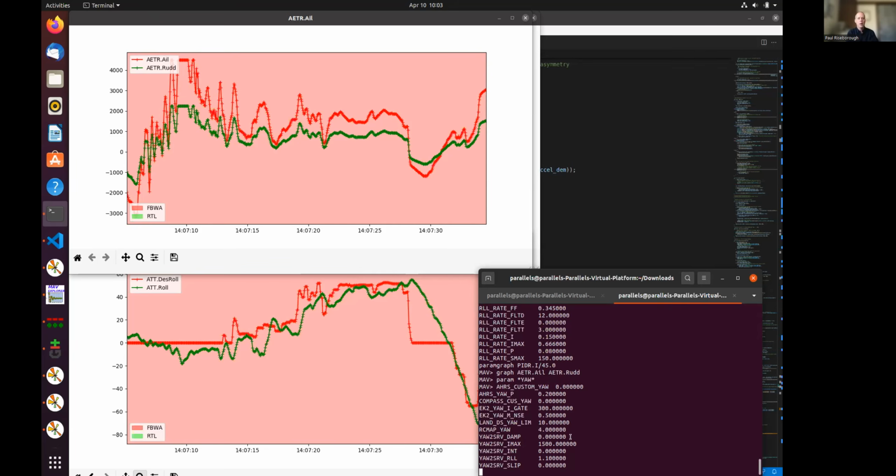Yeah, you can see here I had differential. Also, they weren't running differential thrust for rudder either. I just had two servo outputs with function 7.0, which I think is just normal throttle. So they weren't running differential on the throttle.